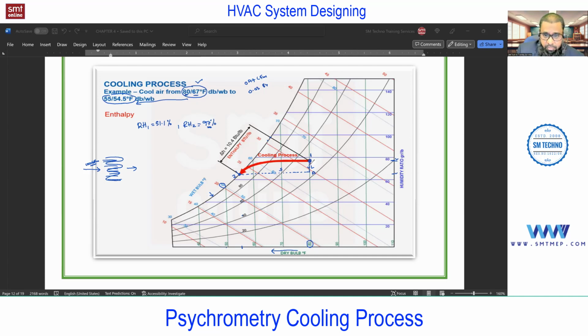It means, you see, with the cooling process, RH increases. So this is not the desirable condition. No? And at this level, just remember, I'm talking about only cooling. I'm not talking about dehumidification. Because of cooling, because of this latent heat, the moisture decreases, and as moisture decreases, the humidity decreases. What will happen to the relative humidity? Relative humidity increases. You see, in this case, okay, let me write all these points, then you'll get the clear picture. Now, the second point is the dew point temperature.